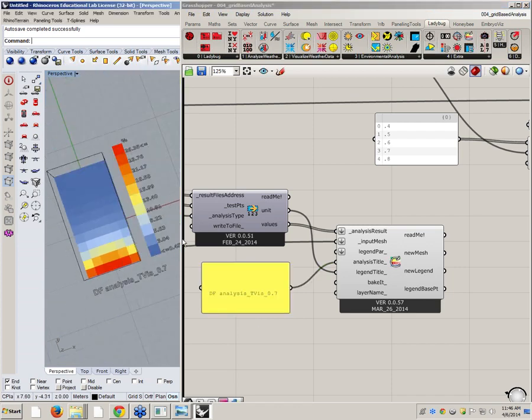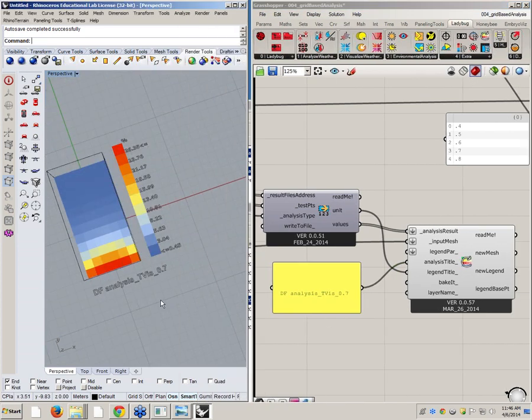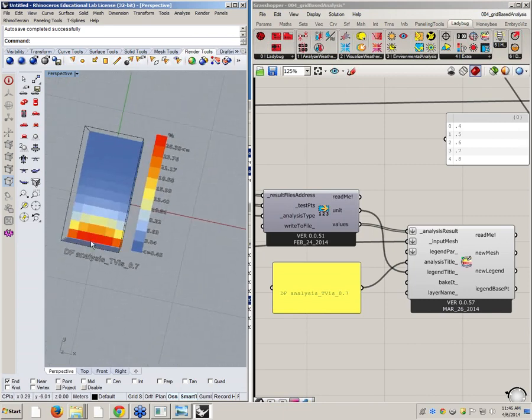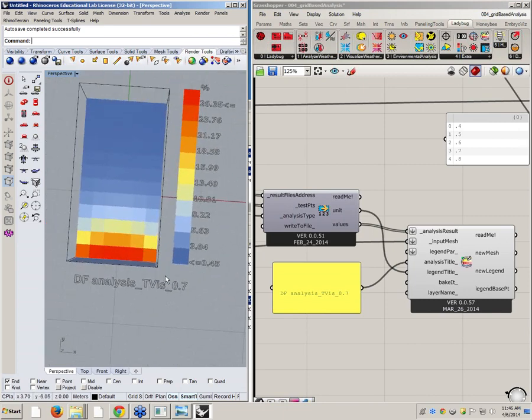So now you have this thing set up, right? And you can see the values. And now this is not a useful graph because we are running a daylight factor simulation, and what we want to see is what is the area that we have between 2% and 5%, right? But these colors don't show me something useful really. I want to go to the client and say, hey, look at this.